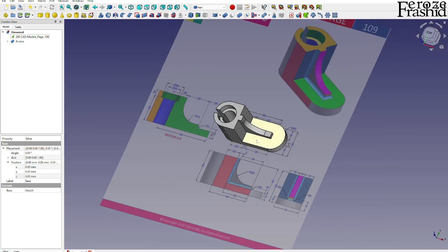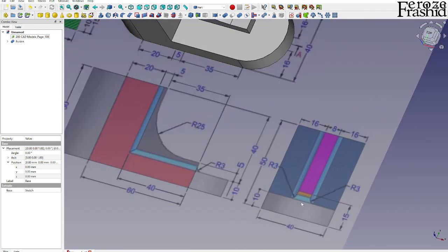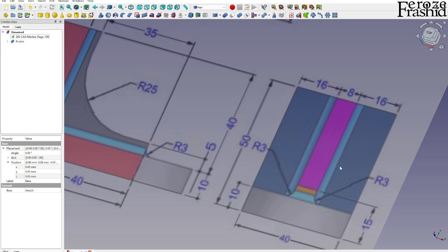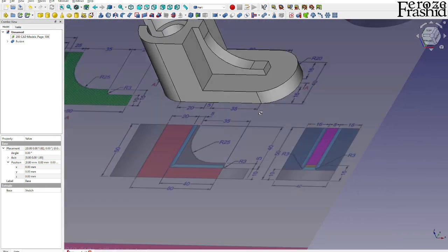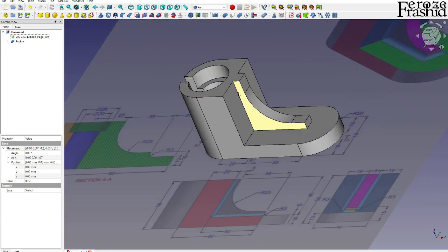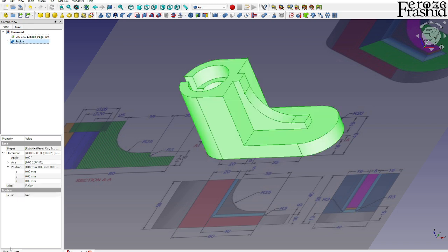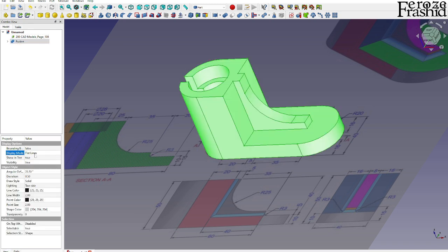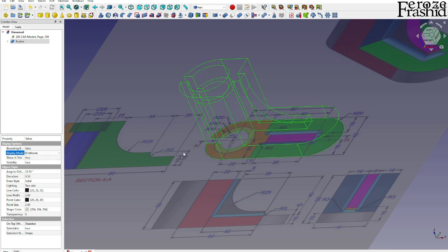Almost there. The last thing is to do a 3 millimeter fillet. It feels like those will be welding, and I'll have to select this line to do that, which is tough. So let's go to the view, and in the display mode, go wireframe.